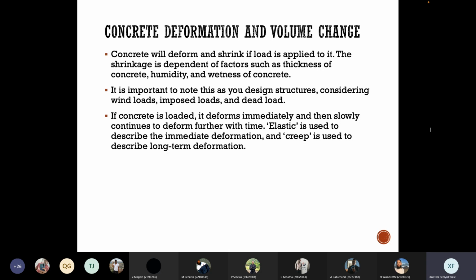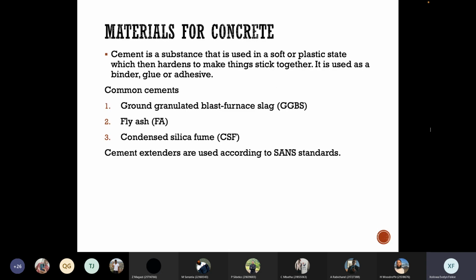So that's what they're talking about. Under loading. So it's not like when you just place it there on its own, it will start shrinking. No, it will shrink because it will be under loading, right? And pressure. Let's just say that. So please note that as important information because you're going to use it moving forward. So if you are asked, does concrete shrink? Then just because it's a solid particle, don't say no. Be able to explain that if under compressive loading, then it is able to shrink, and these are the conditions and whatnot, right?